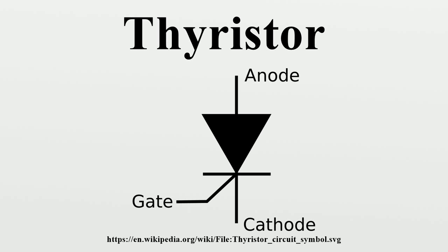A thyristor is not a proportional device like a transistor. In other words, a thyristor can only be fully on or off, while a transistor can lie in between on and off states. This makes a thyristor unsuitable as an analog amplifier, but useful as a switch.